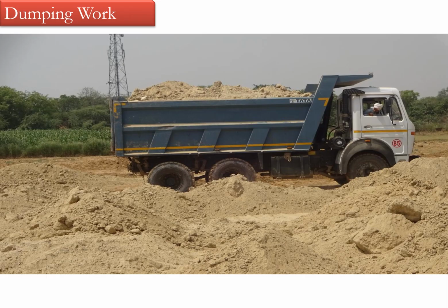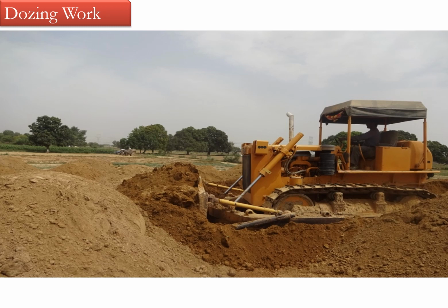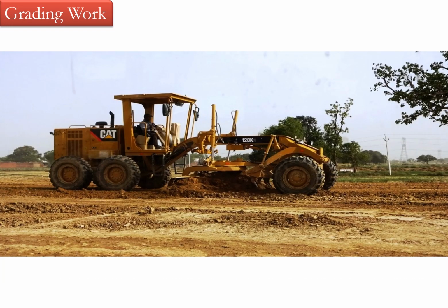This is the process of dumping which is carried out at project sites using high-bar or big vehicles, where the capacity of each dumper is to the tune of say 20 tons or 25 tons. Then you have an equipment called a dozer, which dozes the dumped material and spreads it across in order to get a uniform layer thickness. Then the graders do the grading part, which will try to maintain the camber and the line and levels of the material being spread across.